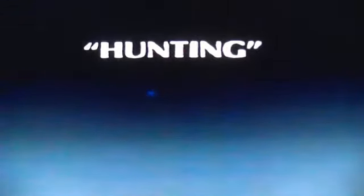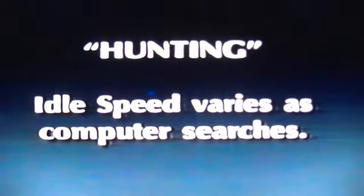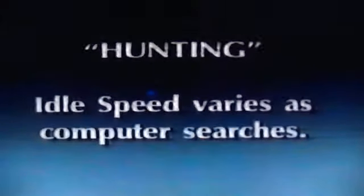The next step is to extend the ISC motor plunger until you hear a ratcheting sound. Following the book specs again, we turn the plunger to set the maximum authority. It's very important that the minimum and maximum settings be to exact specifications. Improperly set limits can cause a condition known as hunting. Simply put, hunting is a situation where, when stopped at a light, the idle speed varies as the computer searches for either the upper or lower limits of the range. If the ECM can't find either the upper or lower limit, it continues to hunt for it. Needless to say, this is a very annoying driver complaint.